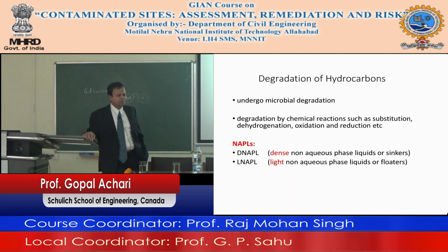So the light ones are on top of the water table, right? And the dense non-aqueous phase liquids have a specific gravity greater than 1, which means they sink in the water. So which is a bigger problem? Why?